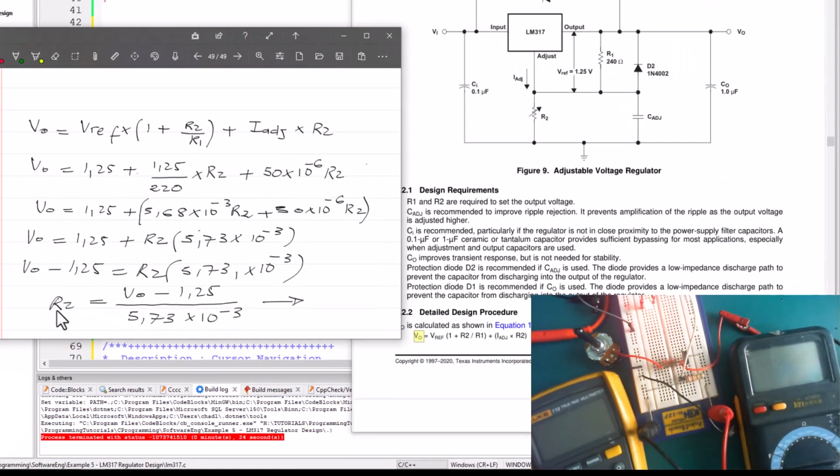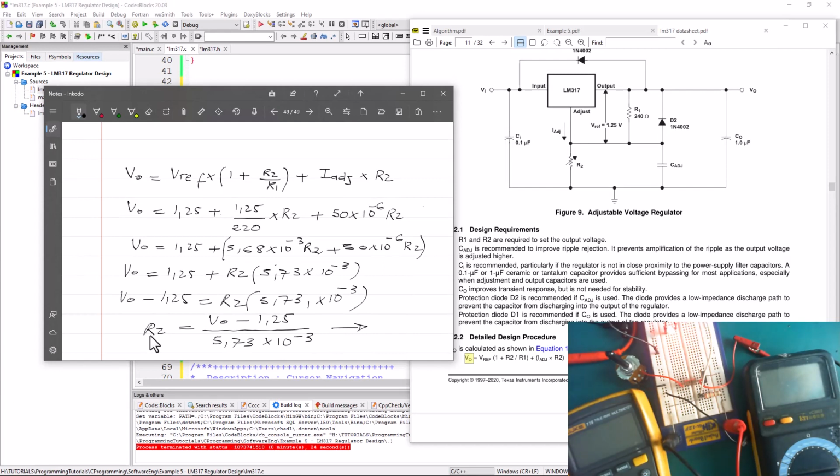So I can round it, because you want to find a 654 ohm resistor, so you can round it to like 660 ohm or 640 ohm, to a standard resistor value that you can find. So which means if I take a 660 ohm or a 680, 670 and place it in here, I'm going to get a voltage that is going to be near that 5 volt that I just calculated.